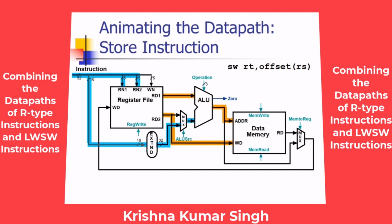MemWrite should be 1, MemRead should be 0. The operation should be add, because we only want to add the base address with the offset to find the address of the memory location. So the operation here should always be add for the store. And ALUSource should be 1, as I mentioned before.